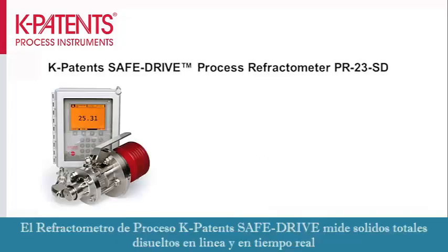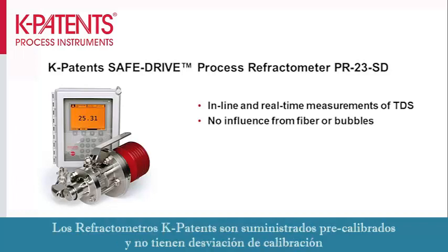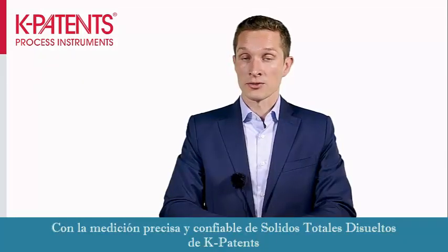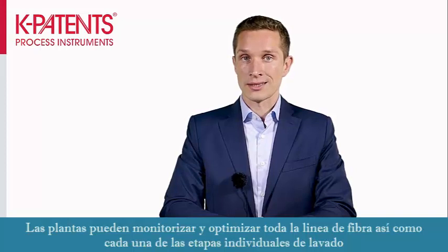The K-Patents Safe Drive Process Refractometer measures total dissolved solids in line and in real time. The refractometer measures dissolved solids selectively without influences from fibers or bubbles. K-Patents refractometers are delivered pre-calibrated and have no calibration drift, making them the optimal measurement solution for process control. With K-Patents accurate and reliable total dissolved solids measurements, mills can monitor and optimize the whole fiber line as well as the individual brown stock washing steps.